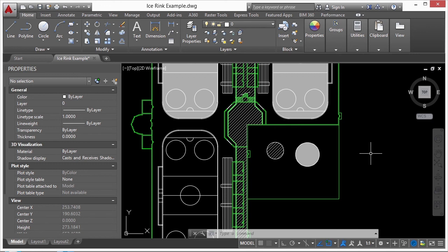Now, this is probably one of the least complicated commands in AutoCAD. There are no settings for it. It's just a select, right click, and you start drawing. It's very simple. It is limited because you can only do what's already in your file. But the add selected command will be a huge time saver once your file has some content in it and will help you continue drawing correctly.